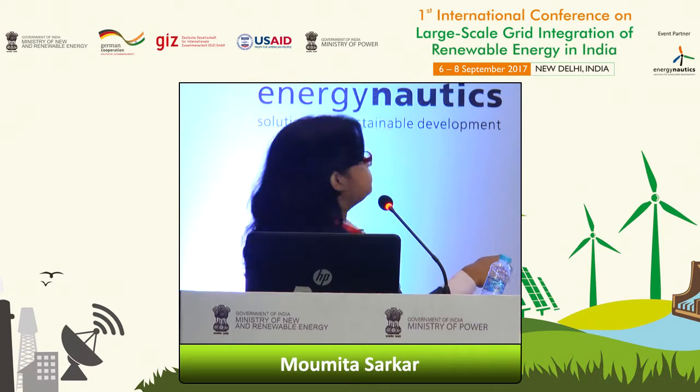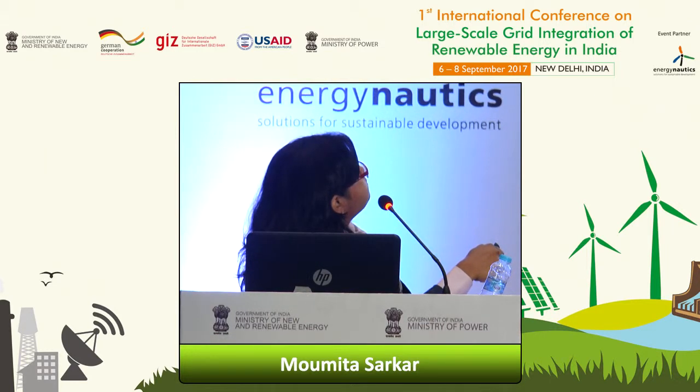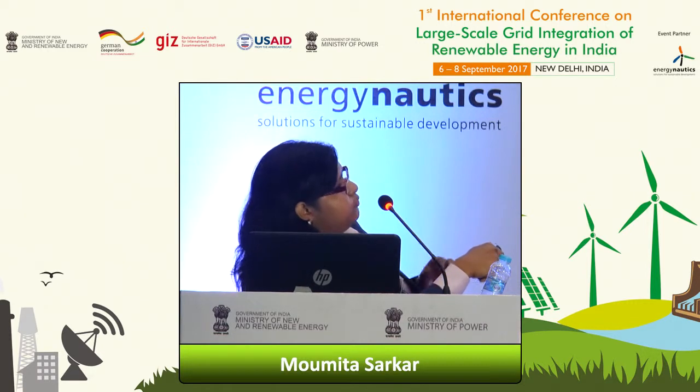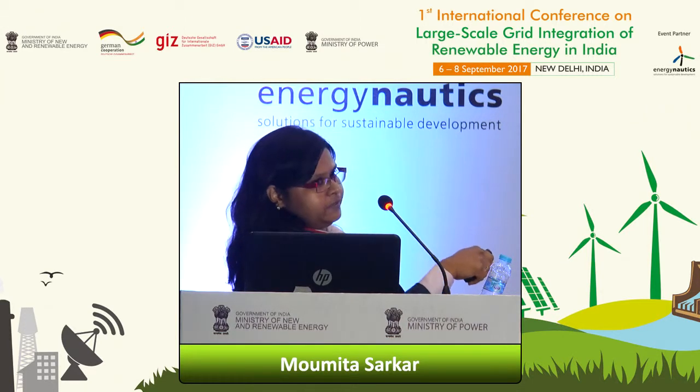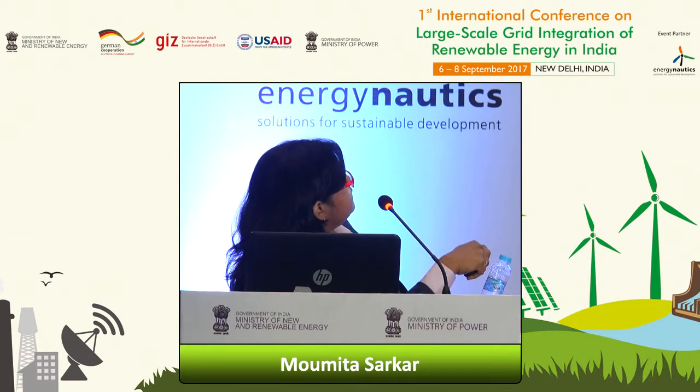The wind power plants are expected to remain connected to the grid even in this region. So it is expected to withstand a voltage dip of around 0.2 pu for about 500 milliseconds. As reactive power injection is prioritized during voltage dip, this is the reactive current injection requirement during faults, and this has to be provided within 100 milliseconds.